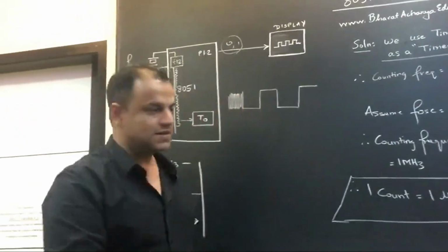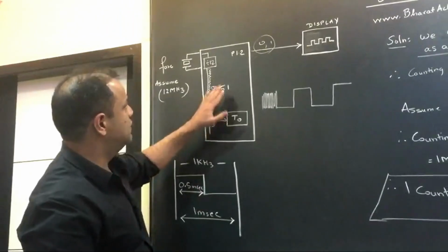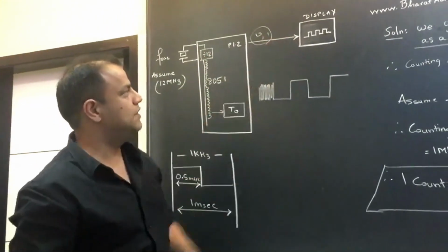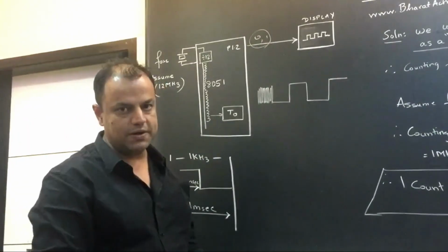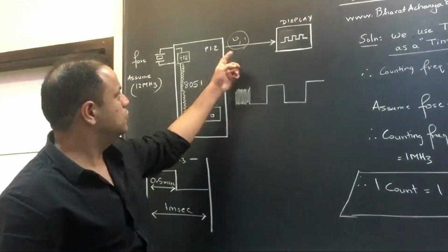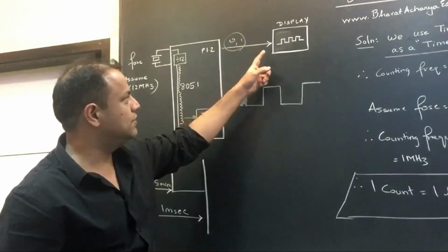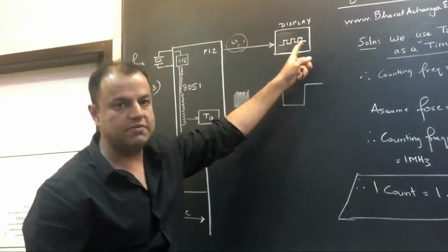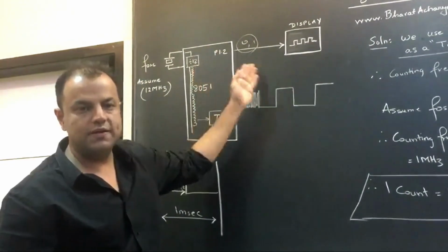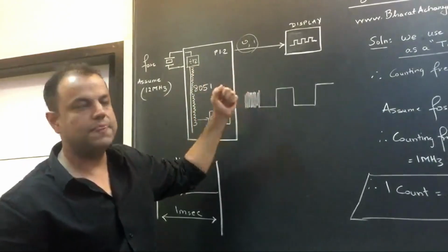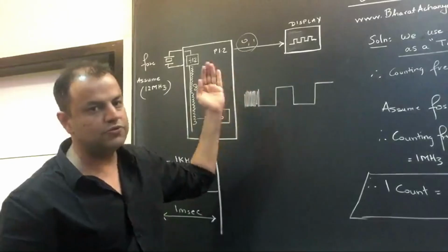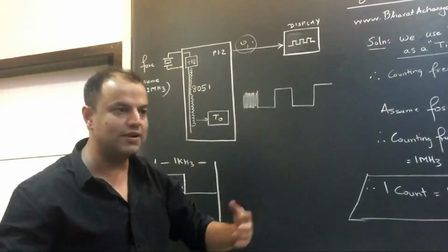Now, first let's understand the question. This is 8051. This is port 1.2. That's any port line on which there is a display device connected, like a CRO. Everybody knows what's a CRO. You send data, it makes a graph out of that data. So you go on sending 0, 1, 0, 1, 0, 1. It will give you a square wave. So that's your program. Send a 0, send a 1. To send a 0, you need the instruction clear. To send a 1, you need the instruction set P. So clear P1.2, set P1.2, put it in a loop, you get a square wave.